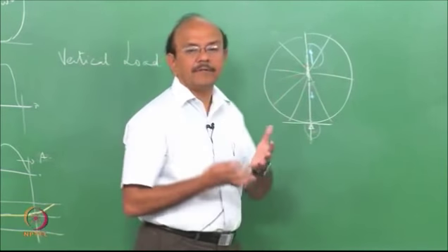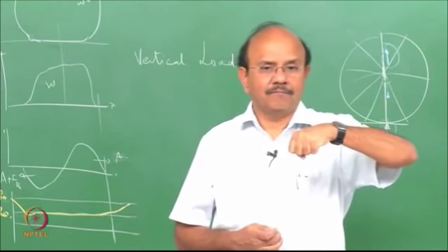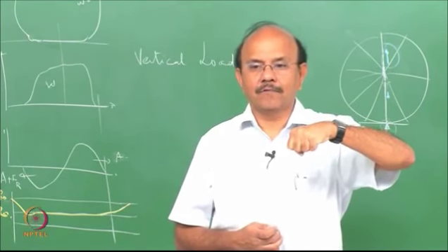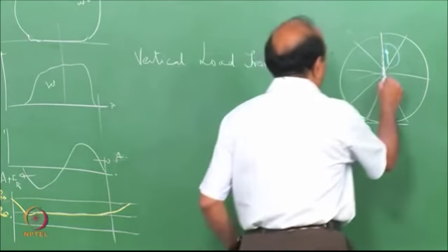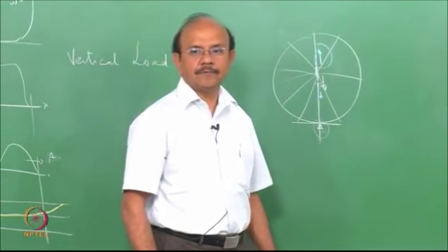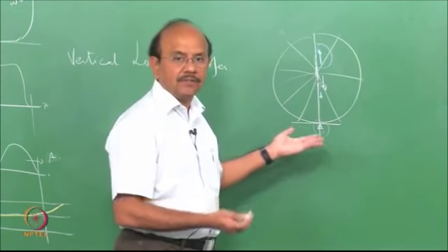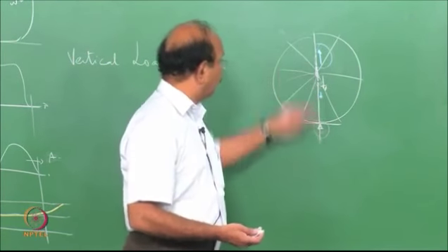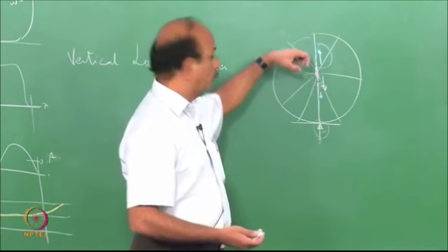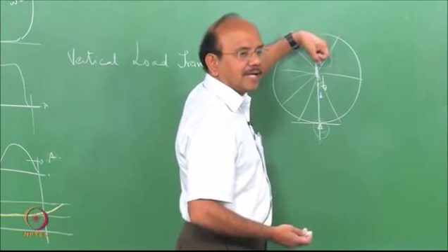This hanging here is what holds it. So there are a number of forces: the load that's acting, and the spokes which have an initial tension. It's a ground reaction. So the equilibrium demands that the whole wheel hangs the axle from the top.